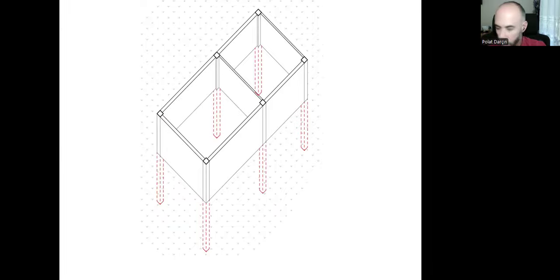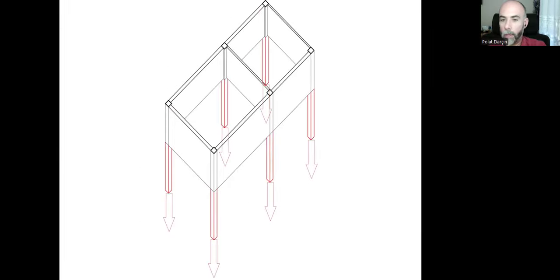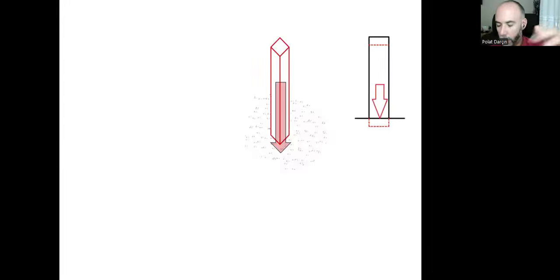These will be the foundation columns and each one will end on a piece of ground, and they will transfer the loads to the ground. However, because of the sizes of these columns, when we apply the loads, even if there is no problem with the bearing capacity, there is a probability that they will be buried inside the ground like nails as we apply the loads over that.